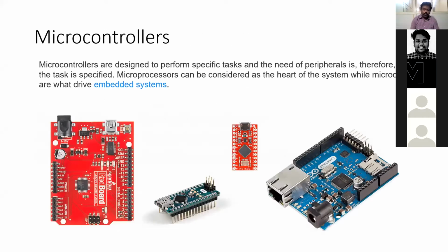When you're talking about general microcontrollers, more commonly we use them to do specific tasks, as I showed here, comprising Arduino, Raspberry Pi, or the recent version Arduino boards. The recent Raspberry Pi versions are 4A and 4B. Whatever the version, they all work for specific logic applications, and we have some limitations, especially on the clock frequency side. With Arduino, you can do specific functions, but it is very limited. If you go for Raspberry Pi, it works very similar to a system level, but it is limited in memory, limited in RAM, limited in many aspects.